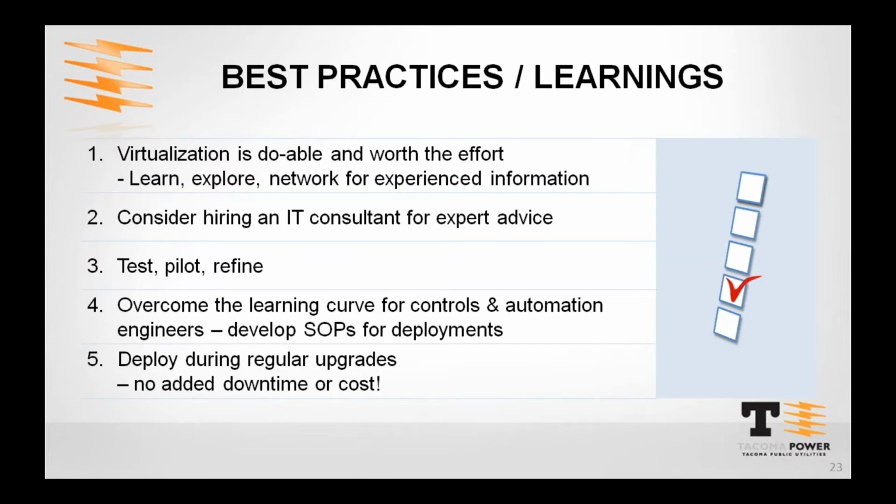You want to be able to test, pilot, refine the process, and then overcome the learning curve for controls and automation engineers, developing those standard operating procedures that we talked about for deployment. We actually have instructions set up on how to install the Windows operating system on the server, how to put together virtual environments, and install GE iFIX on those environments, and the licensing and all that. So we've got a pretty good system set up as far as getting an environment put together.